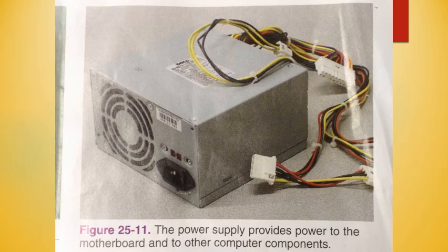The ATX power supply connection on the motherboard is a single unit that is keyed. This means that the connection to the motherboard is designed so that the power supply's connector can fit only in one way. Earlier models, such as the AT and XT, used a pair of motherboard power connectors. Although these connectors were also keyed, technicians had to use care in connecting them to the motherboard because they could easily be switched, resulting in a damaged motherboard. A memory aid in correctly connecting the two power connectors to the motherboard is "black goes to back." This means that the black wire on each power connector should be next to the other when plugged into the motherboard.